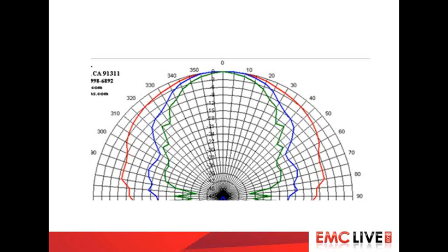Equally important, if you look to the left of the 0 boresight line, I'll read this for you because it's a little bit fuzzy. You have 0, the outer circle. Then you have -3, that's -3 dB, -6, -6 dB, -9, and so forth, all the way down to minus goodness knows what, lost in the noise floor. So you can plot on here the power relative to the boresight. Relative to the boresight, if I move 5, 10 degrees and look at the green line, it's dropped about 1, maybe 1.5 dB at the 10 degree marker. So there's actually quite a lot of information here if you know how to use it.